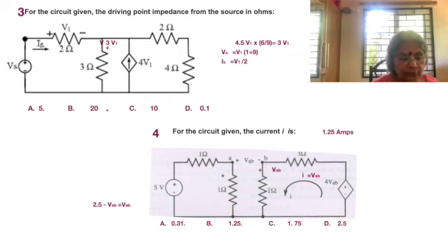Now here this will be useful. So where's the dependent source? It is 4 VAB, and this VAB is across A and B as shown between the 2 loops. Let's look at the right loop first, because we see that 4 VAB is a voltage source, and it is encountered by 3 plus 1, 4 ohms.